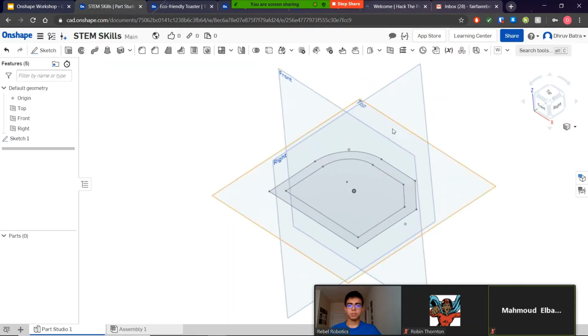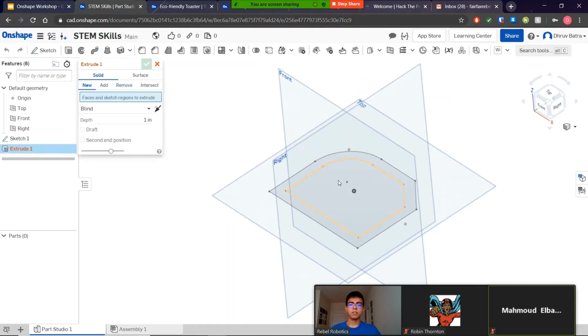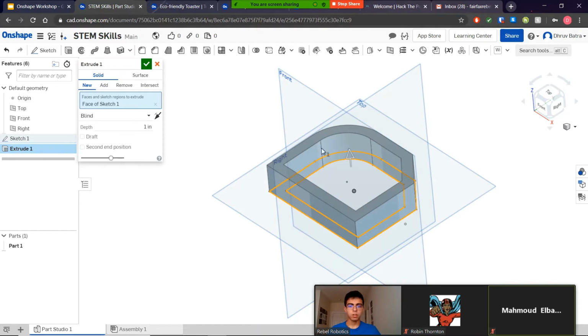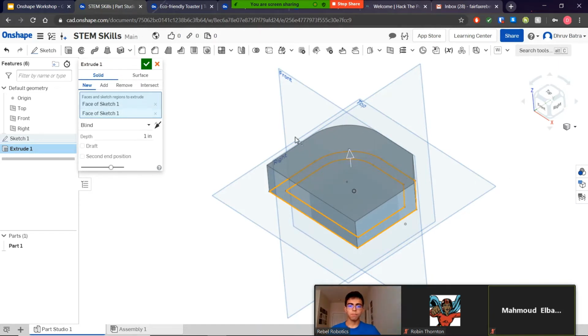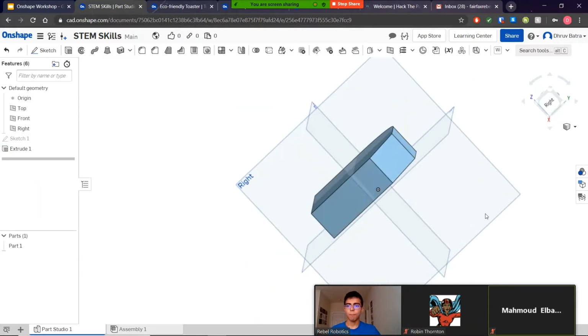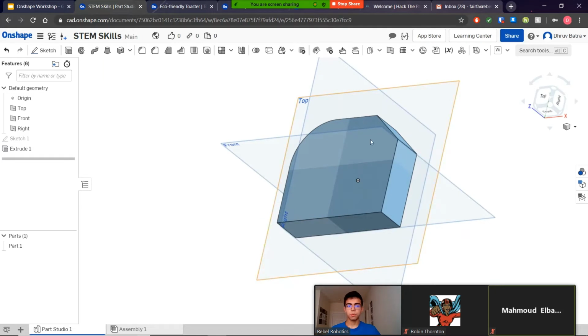I just showed you that, but here's something you should know is that whenever you are manipulating sketches, it chooses the closed boundaries. So thinking about like using the paint tool, right? If you have a closed boundary and you want to have multiple, you have to select multiple. So, you know, keep that in mind. Use that to your advantage when you're designing. So that's the extrusion tool.